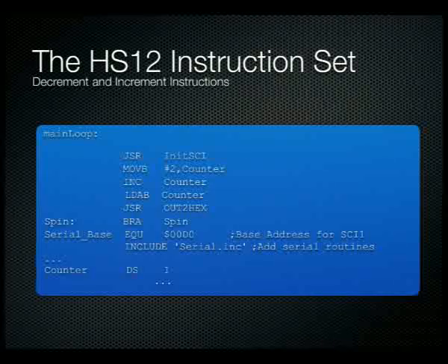And then what I do is I then simply load the value that counter refers to into accumulator B. Okay, because I want to be able to print it out with out2hex, it has to be in accumulator B. So I load it into accumulator B, and then I JSR out2hex, so therefore I get the value of 03 printed onto the screen. So you can see both these examples do exactly the same thing, except one was incrementing a register, this one is incrementing a memory location called counter.